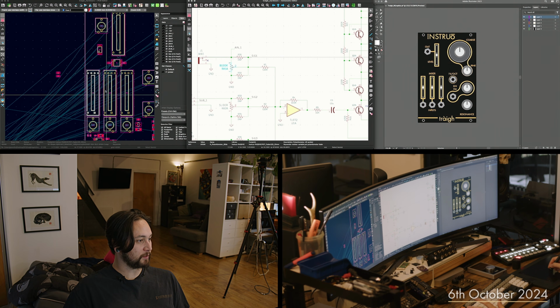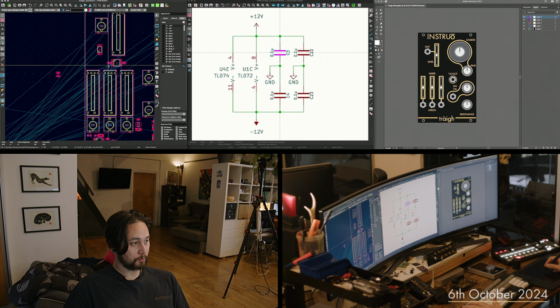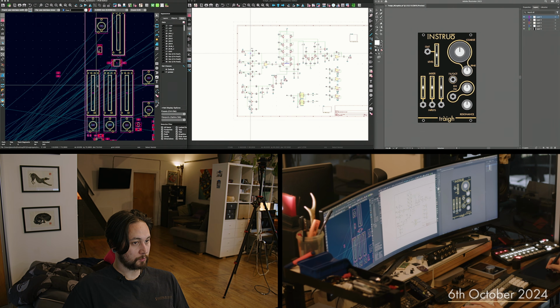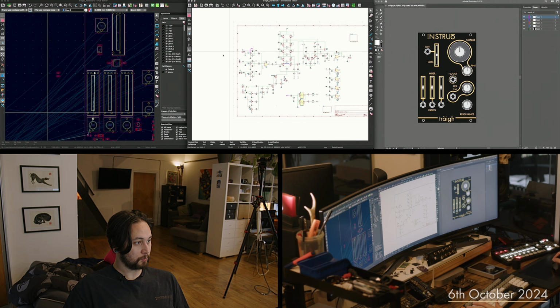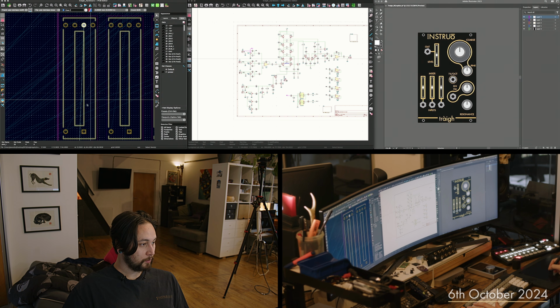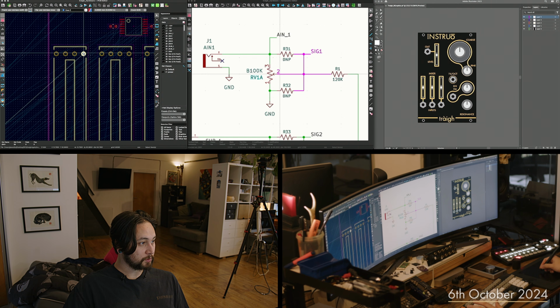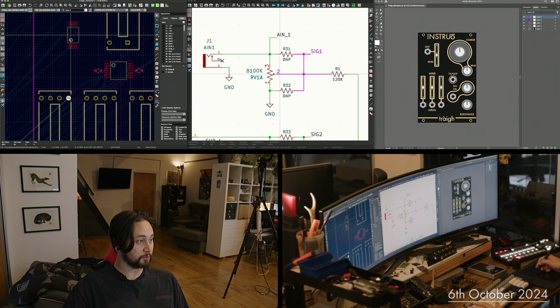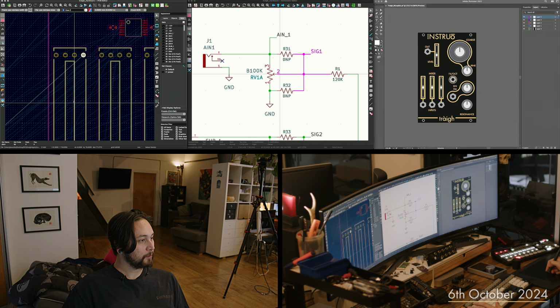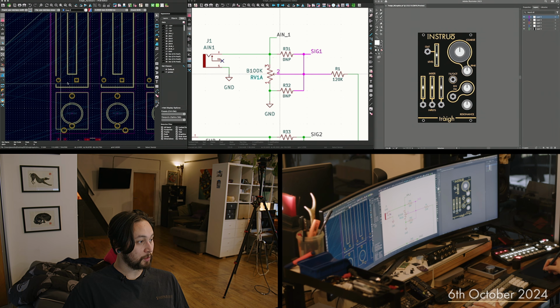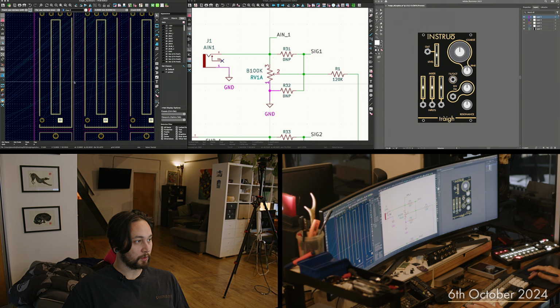So this is the input 1 fader. So that will be pin taper moves, which is pin 2, and that goes towards 3, which is, oops, there. So that's pin 3. The taper is pin 2, which is there, which is what I need to branch out to my op-amp. And pin 1 is ground, which is down there, but ground's going to be common anyway.